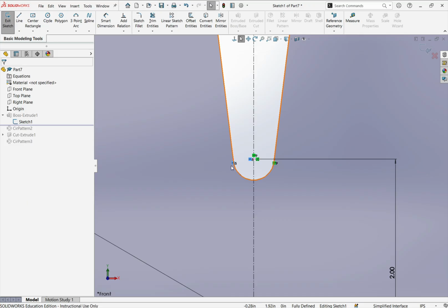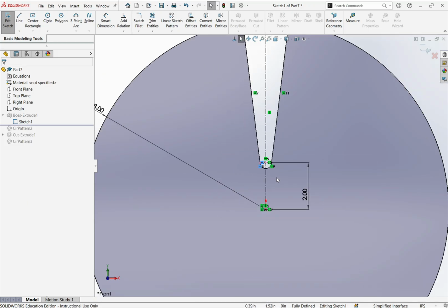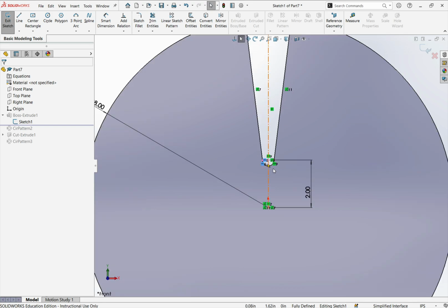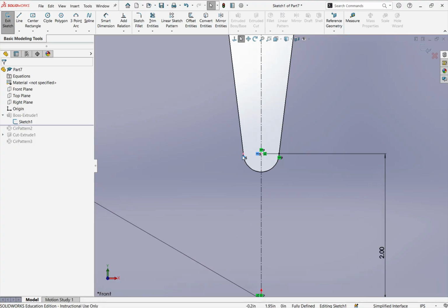So I don't actually have any dimensions about the radius. So I'll zoom back out. I don't have a radius on that. Should surprise you. As you're watching this video, think about why I don't need it. Okay? If I have a distance away of 2 to that line, and I have these 2 horizontally to each other, I fully defined that this is going to be a semicircle.